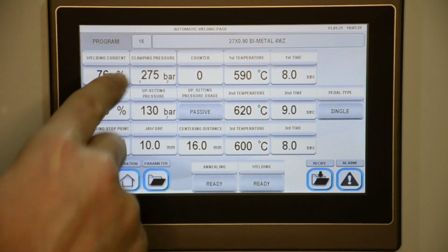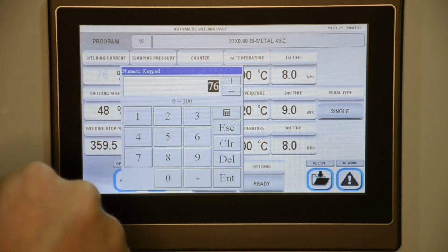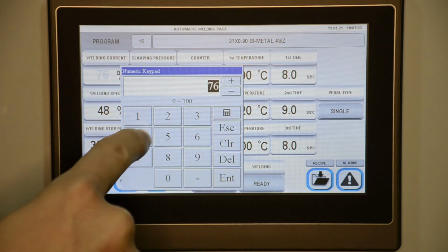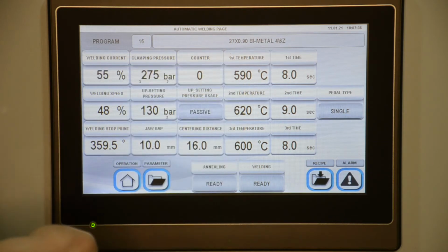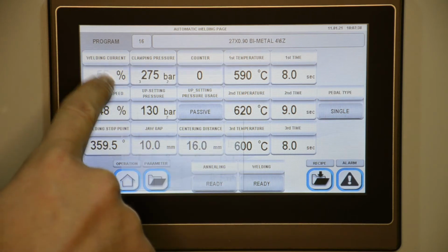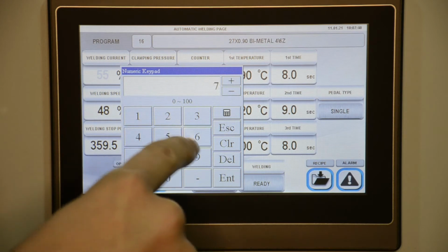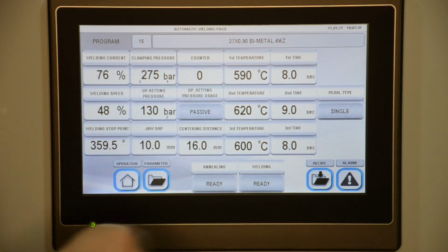The welding current refers to the percentage of the transformer value to be used while welding. Current value is adjusted by the thickness and width of the blade that we would like to weld. The only point that operators have to be sure of is that during the welding, flash has to be continuous. In case of a break in flashing, this value should be increased.